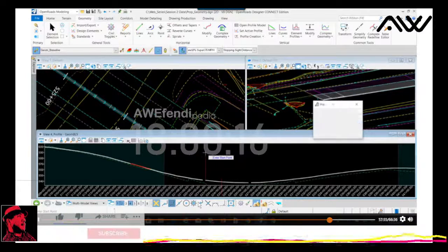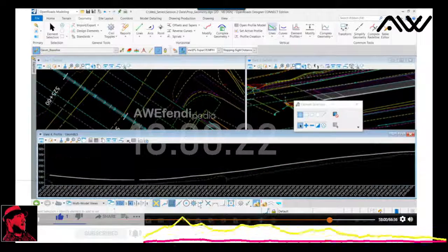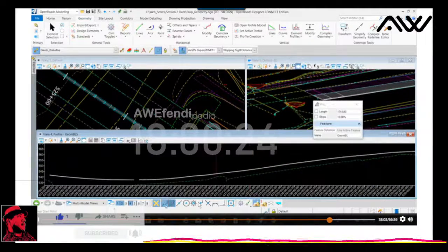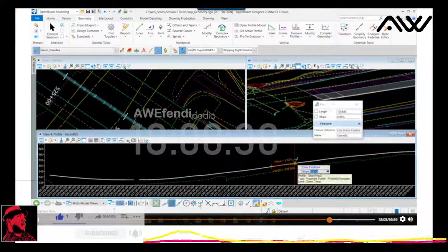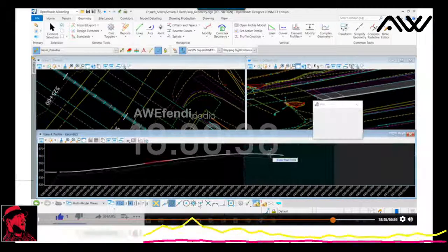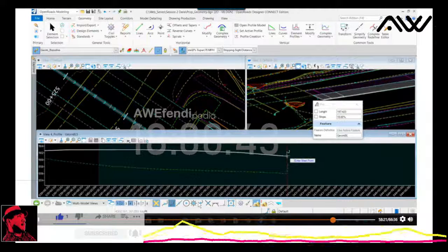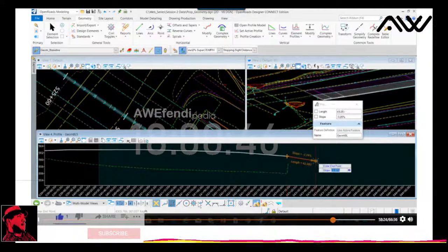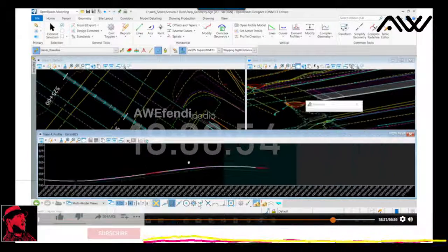And let's go to the next tangent area. Again, same process. I can follow along here. And the next section, we want to hold to a 3% grade. Okay. And then finally, on the very end, we've got just a small tangent. Since we end in a curve, let's jump. I'm going to snap there, and we'll make the last segment a minus 1.25. And place that.